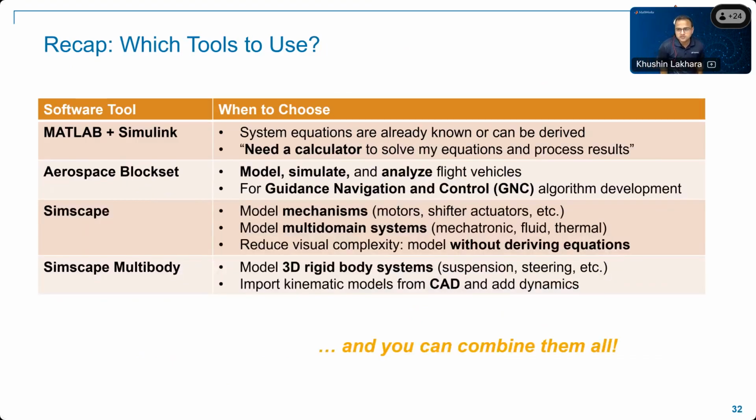But remember, MATLAB and Simulink tools are available. You can use MATLAB and Simulink when you already know the system equations and you need a bigger scientific calculator to solve your equation and process the results. Use the aerospace blockset and UAV toolbox to model, simulate, and analyze your flight vehicles for guidance, navigation, and control algorithms. Use Simscape when you need to work on the mechanisms or do multi-body simulations. So all these tools are available and all these are part of MATLAB.